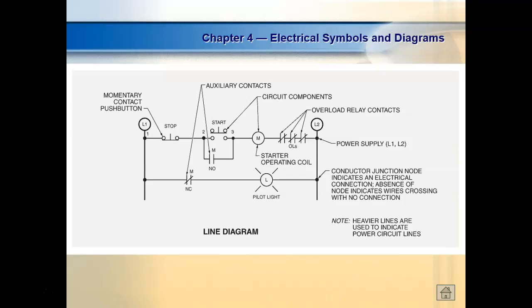Big multi-voltage motors in the industry, a lot of your motors have the ability to be wired to run off different voltages. And why? Because most industry has multiple voltages there. Now, if available where you're at, which would they do? Would they wire it for high voltage or would they wire it for low voltage? Why? It takes fewer amperes to run the motor, which means they can run smaller gauge wire out there. But what you do is you literally rewire the motor. So you have a little box on the side of it, you take it apart and rewire it.